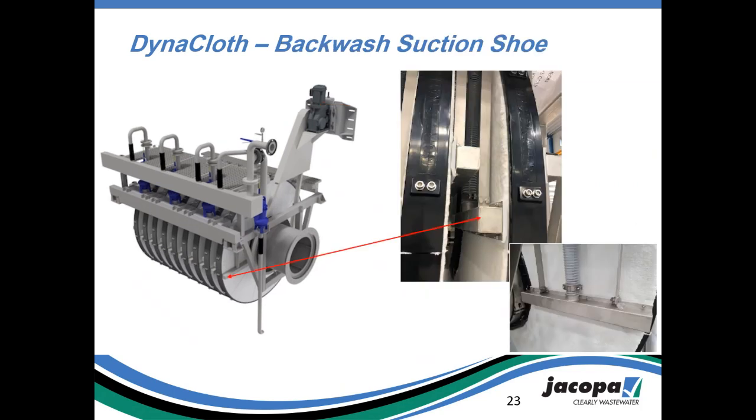These are the suction shoes. That's probably the word I was trying to think of earlier that didn't come to mind, which will clean the cloth. The cloth has to lie a particular way, depending on whether it's an inside or an outside cloth. They're slightly different colours, which make sure that the pile lies in the correct fashion to work in the particular application and allow for the direction of rotation of the shoe. And obviously 3 of those act at one time to clean the discs.